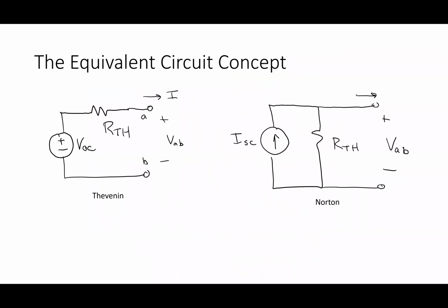Okay. So one thing to remember is, there's the Thevenin equivalent and there's the Norton equivalent, and they are equivalent. The Thevenin equivalent basically says VOC and RTH are in series. The Norton equivalent says I have a current source in parallel with those. You would call this source transformation to go from one to the other. The important thing for me is that if I look at the voltage-current relationship at the terminals, they are identical for these two circuits.